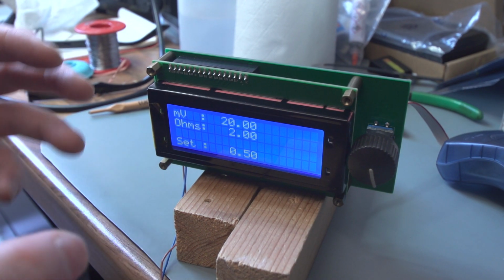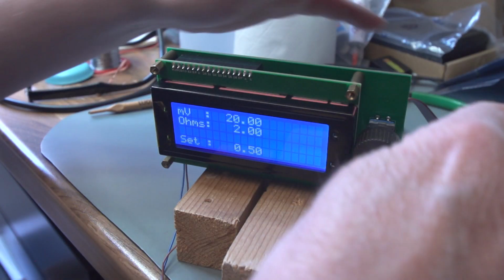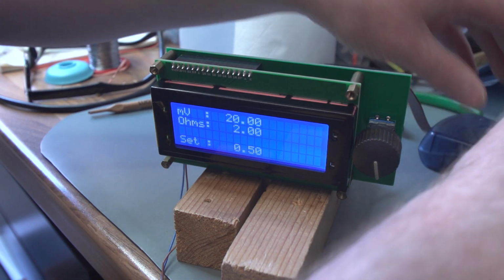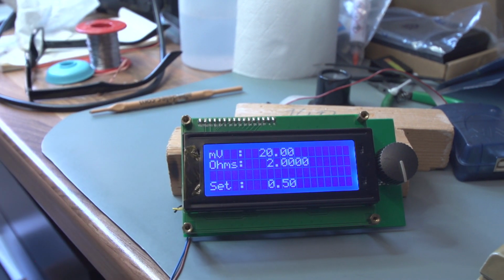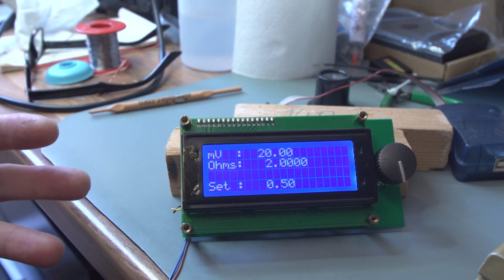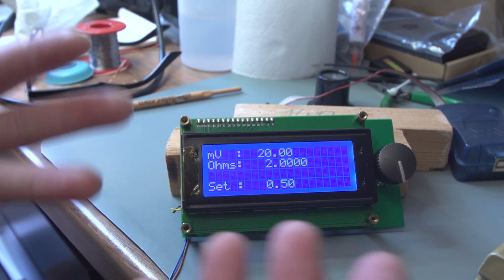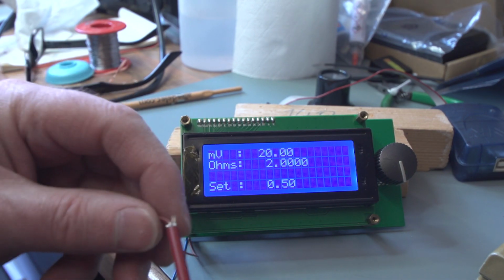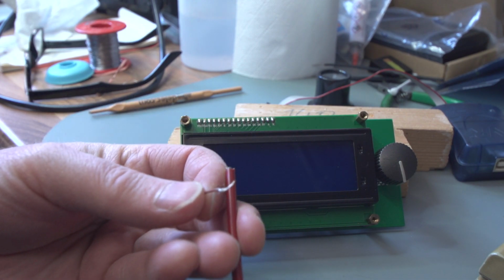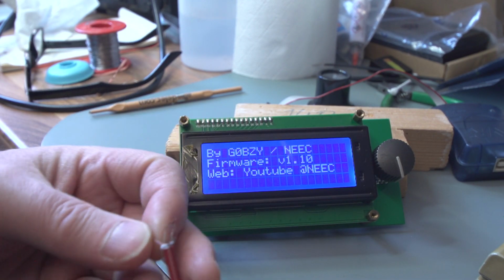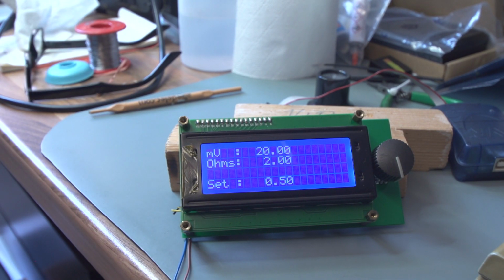And here we are back again. First things first, it booted up and we've got a display. I need to disconnect the programmer, and it may crash the unit. Sometimes that happens when you disconnect it. What we're really interested in now is whether it's clocking at the correct speed. We know that by the splash screen time, it should be something like 2 or 3 seconds, not like it was before. So let's disconnect the power with this extremely fancy switch I've got going on here. Put the power on. 1, 2, 3. There you go. Right. Fixed.